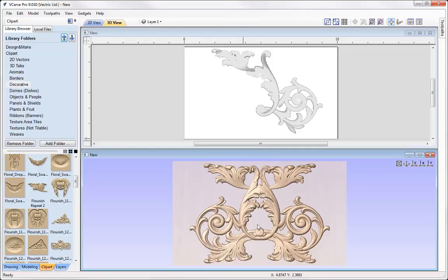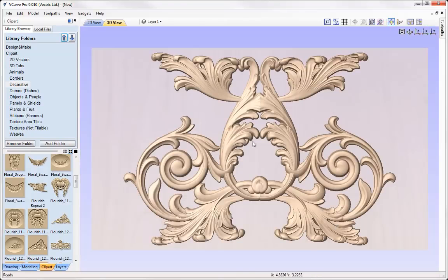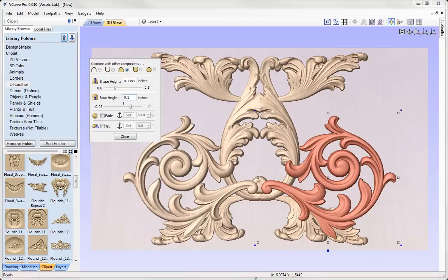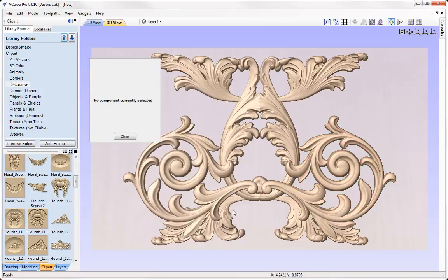So here, what we could do is think about the actual component heights. A lot of our components are just blending into each other. So if we maximise the 3D view, we can see that we've got this area being obscured by certain components. So we might want to take that, go into the properties here. Could look at adding in a very small base height, so make that 0.1, just so we're lifting that up in front. And so now the flourish that we've mirrored up from the top left quadrant is now sat proudly, or well, discreetly in the background.